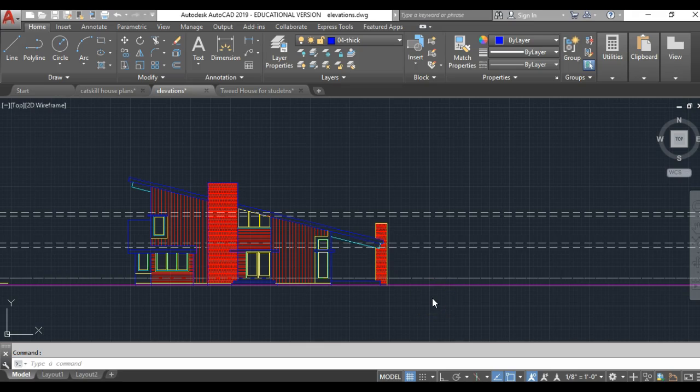Then there are a couple other rules we use when we're determining the line weight in elevations. The first is edges. The outline of your building tends to be a thicker line weight than stuff that's more internal. That's actually the important rule for elevations. I guess it's true for sections as well. And so you sort of want to highlight the object.